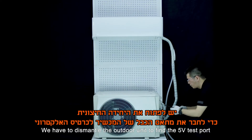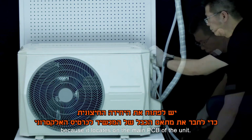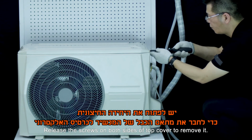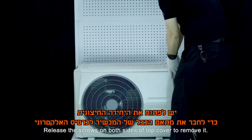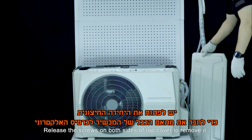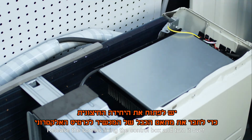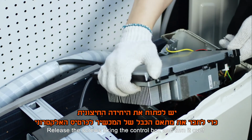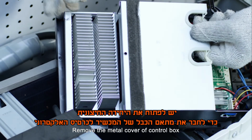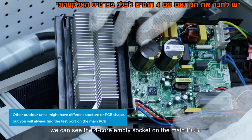We have to dismantle the outdoor unit to find the 5-volt test port because it locates on the main PCB of the unit. Release the screws on both sides of top cover to remove it. Release the screws fixing the control box and turn it over. Remove the metal cover of control box. We can see the 4-core empty socket on the main PCB.